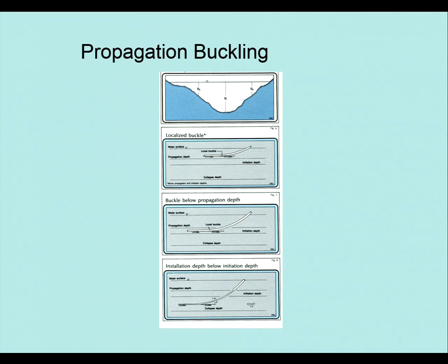Propagation. So all this little chart does, it's not a very good one, is show that if you initiate a buckle in deep water, then that buckle will propagate until the energy from the water is no longer capable of propagating that buckle, and that's the propagation depth.